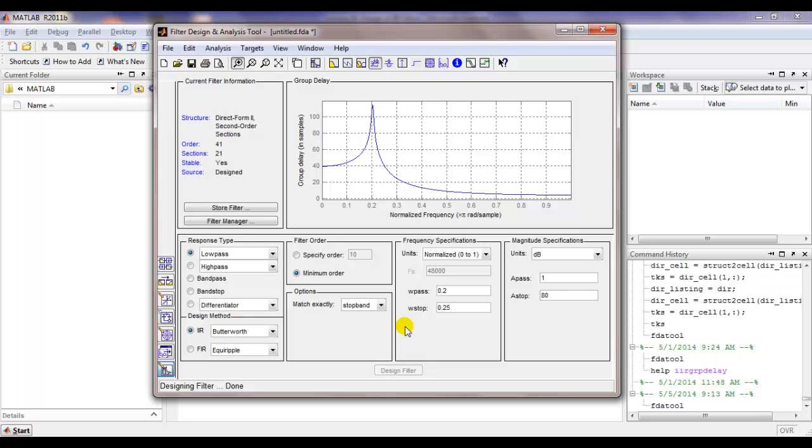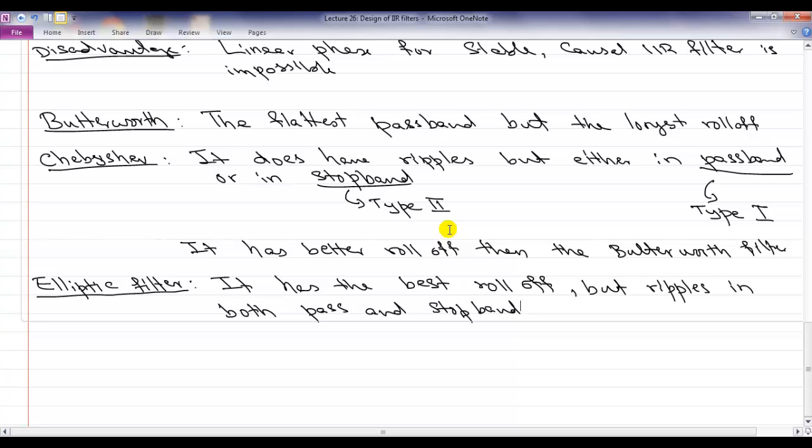So that's all that there is to know about general IIR filter design. A lot more details can be said, but as we talked about earlier, if you are really interested in applications where linear phase matters the most, you probably are not that interested in those details. So that then concludes our discussion of the IIR filter design to the extent that we wanted to discuss it. You should at least have a good sense of what the general principles of Butterworth, Chebyshev, elliptic are, which one is better in terms of order, which one is better in terms of flatness, and so forth. But we are not going to go into any more details.